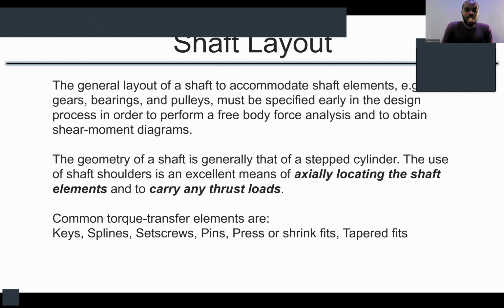Let's talk about shaft layout. How do we geometrically arrange shafts and shaft elements such that they transmit power? It's very, very important. In your design, there are certain principles that you need to follow in transmitting power. A shaft usually accommodates shaft elements, and those are bearings, gears, pulleys, or it could be sprockets, etc.